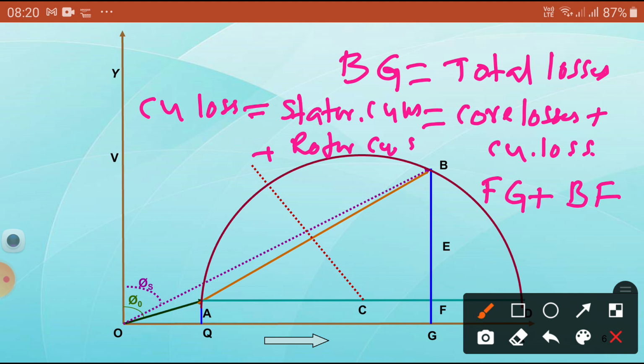Under a blocked rotor test, mechanical losses are 0, because the rotor is under standstill condition. What remains are the iron losses. Under standstill condition, E2 is there with S equal to 1, and some iron losses may occur. At the same time, the remaining power goes to copper losses in the form of heat energy.